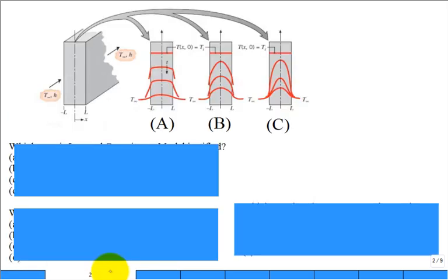Well, remember this? This was helping us motivate our study of the lumped capacitance method. Here's a large sheet of some material. Think about it being very large, but very thin, and the thickness is 2L, so the half thickness is L. It comes out of a furnace. It's hot. It's going to be convectively cooled when it's subjected to fluid, both on this side and that side.